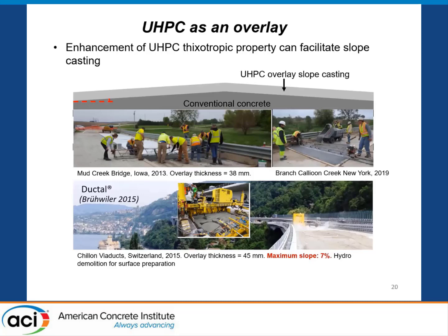This is good for bridge joint casting or closure casting, and for casting complicated precast elements. But it makes it very difficult to cast UHPC on an inclined surface, where a crown design with slope is required.